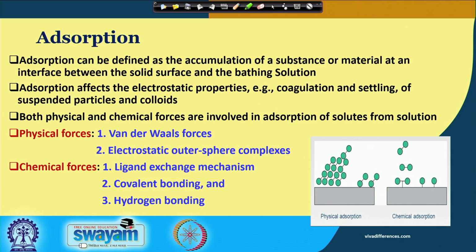Now, adsorption can be defined as the accumulation of a substance or material at an interface between the solid surface and the bathing solution. Remember that adsorption affects the electrostatic properties, for example, coagulation and settling of suspended particles and colloids. Now, both physical and chemical forces are involved in adsorption of solutes from solution.